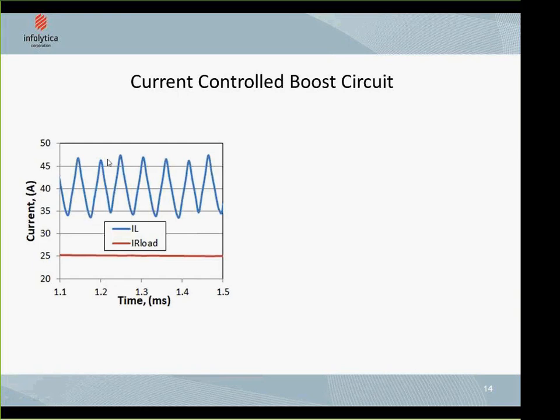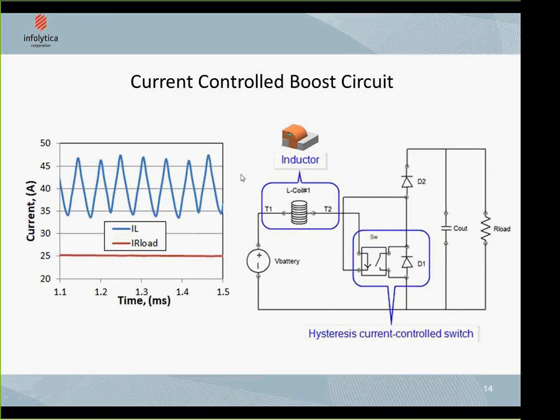We can implement that in MagNet as seen in this circuit. We have our inductor there that is a 3D model, so it will be able to capture most of the effects that I mentioned. And then I've connected it in series with my current control switch, which is hysteresis controlled. And then I can regulate the boost properties of this converter.